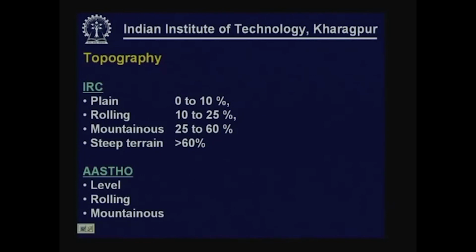The topography is again not the same. As I mentioned, the terrain condition varies so much from one corner to another corner. It may be possible even to construct a facility where the design speed will be as good as the design speed in plain and comfortable terrain condition, but again it may not be economical to try to achieve that.